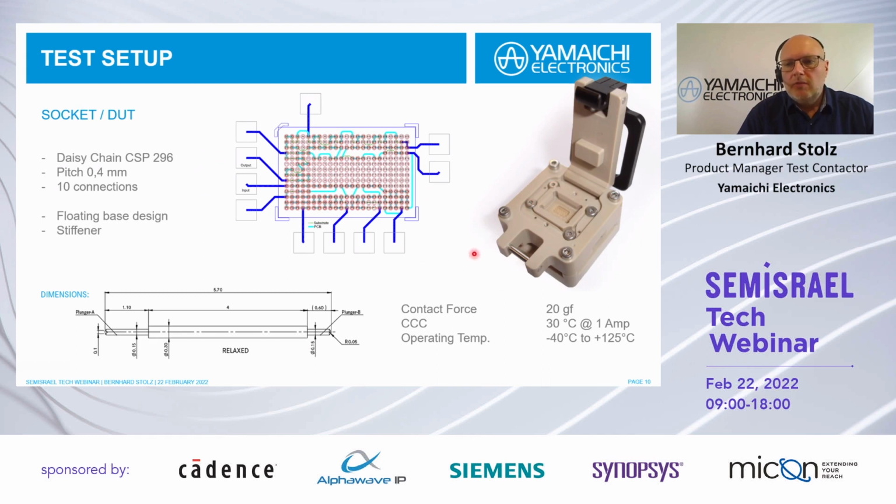We are using a test contactor, which has a floating base design. So the floating base itself is here. This is spring loaded, so it helps to protect the pins when the device is inserted, but also helps to align the device in the socket. It has a stiffener because of the high pin count, but it's a very usual socket.